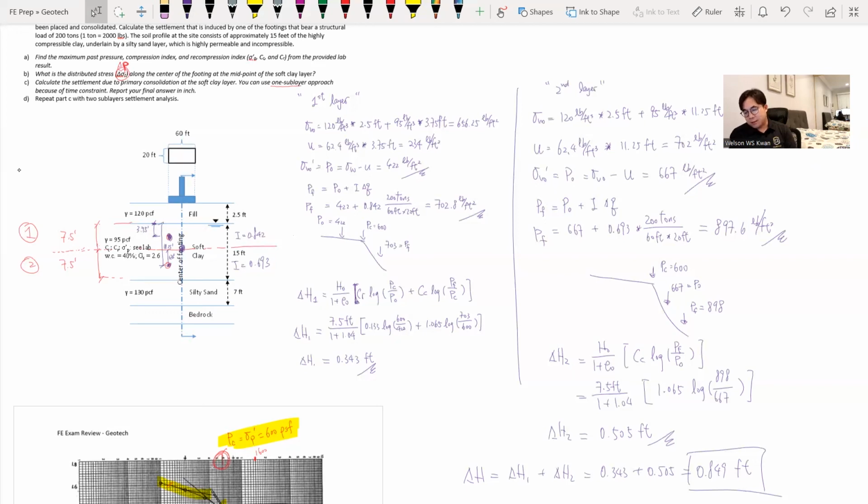In practice, all of these calculations can be programmed in computer computations. You can code it using MATLAB or another language, such that you can set the tolerance, and at the end of the day, you can see how the settlement is affected by the different sublayers. But in learning hand calculations, it's always good to try a few sublayers.